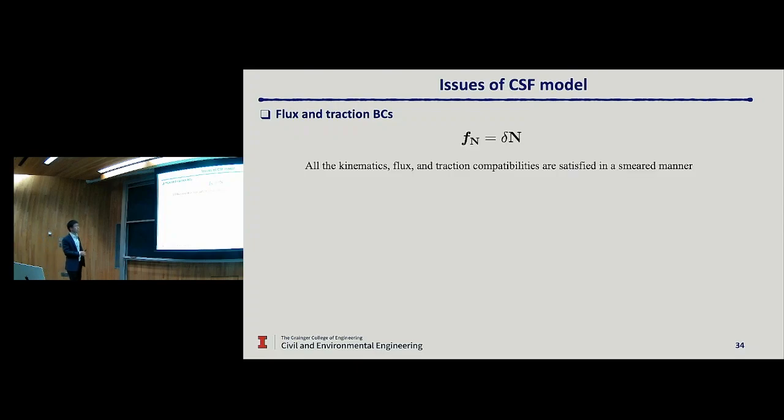Remember, there are several boundary conditions, Neumann boundary conditions, you need to satisfy on the gas-metal interface. Because people couldn't have an explicit representation of the interface, you couldn't just enforce them as a traction or flux boundary condition. So what people do is instead apply them as an interface condition, you convert the interface boundary condition into a body force through a delta function.